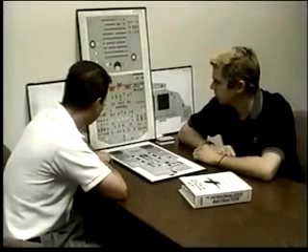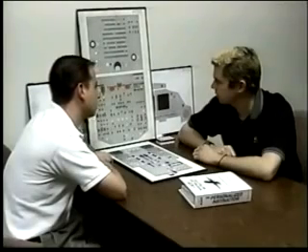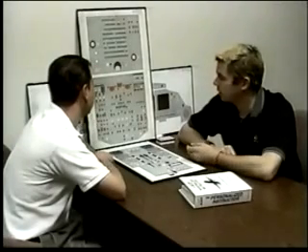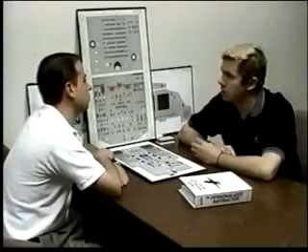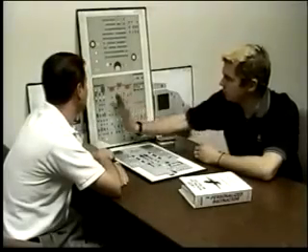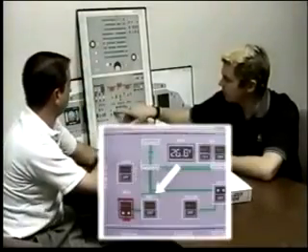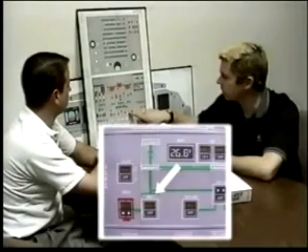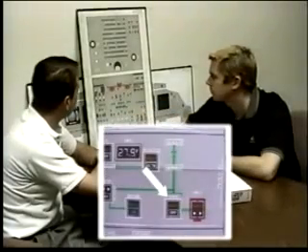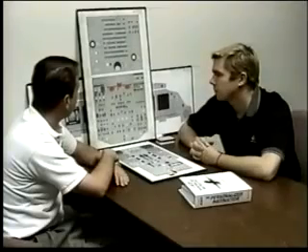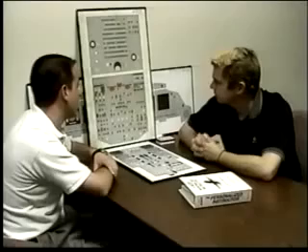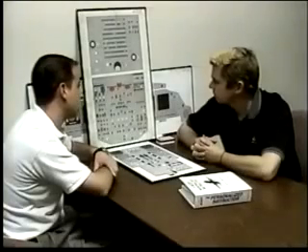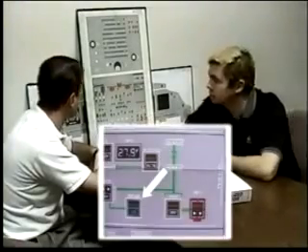Electrical panel. What is the electrical priority? The priority is on-side generator, on-side engine-driven generator, the external power, APU generator, and off-side engine-driven generator. What I mean by on-side and off-side, let's just use AC bus 1: the on-side generator is Gen 1, the off-side generator is Gen 2. Based on that electrical priority, external power is on, you have the APU available. How do you get the APU generator online? You have to deselect external power.